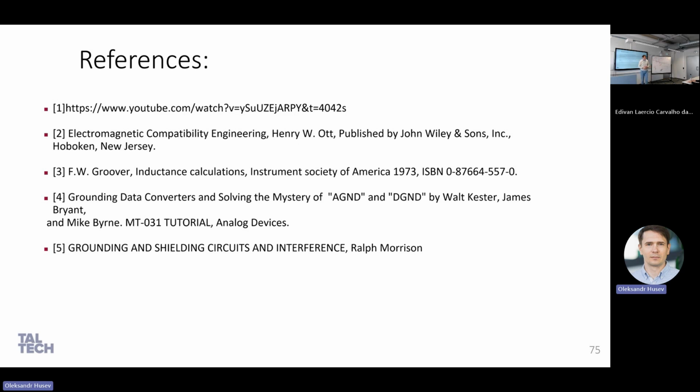What if we don't exactly overlap it? Say we select the source on the bottom layer and drain on the top layer, but kind of shifted. It's possible. If you have overlap in drain-source, capacitance will definitely increase. With no overlapping, with the top layer shifted, capacitance will also be present, but much lower, like 5 times lower for sure.